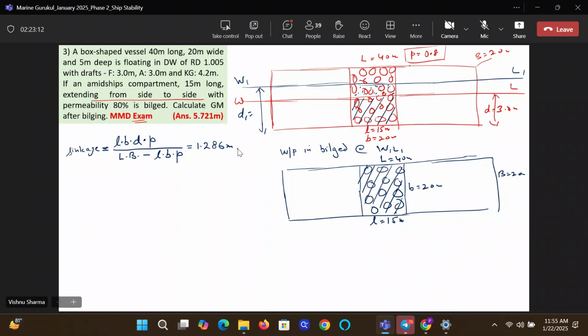Okay, in Simpson's rules, if you are getting volume, what were you integrating to get volume? Volume is integration of which thing? When the volume of the book was being made, what were you adding together to get the volume of the book? Guys, volume you get by integrating what? Area. Water plane area.